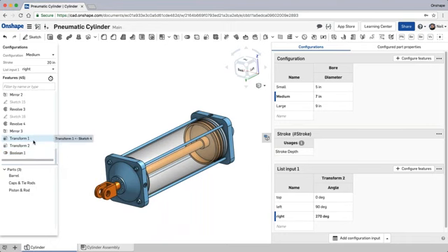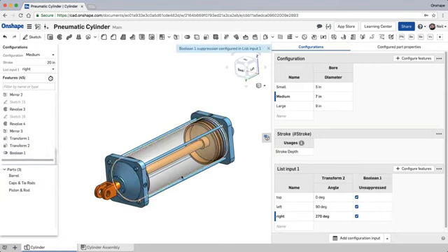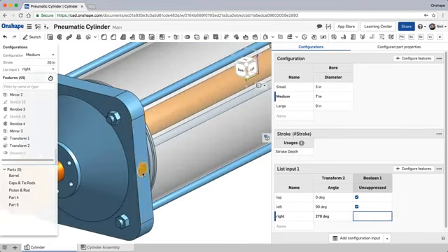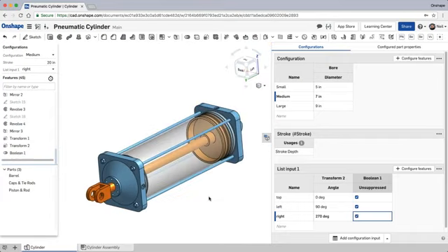So for example, let's suppress that as list input 1, and it's then going to be a checkbox. So if we suppress that, it basically suppresses the cutout, which was this feature here. So again, you've got full control over feature size and feature suppression. And again, for machine design, of course, it's very important because you have all these different ways of making a design modular for different packaging capabilities or anything else that machine might do.